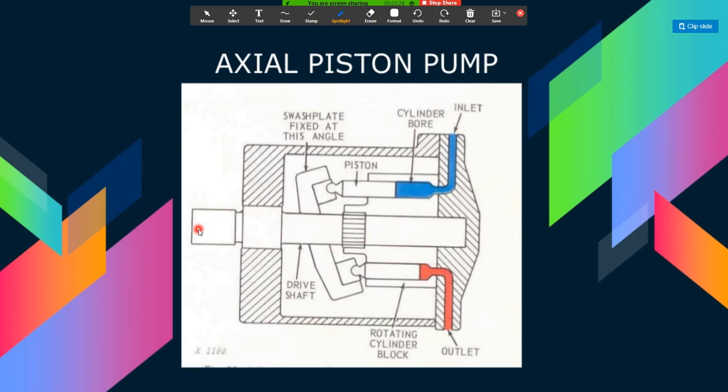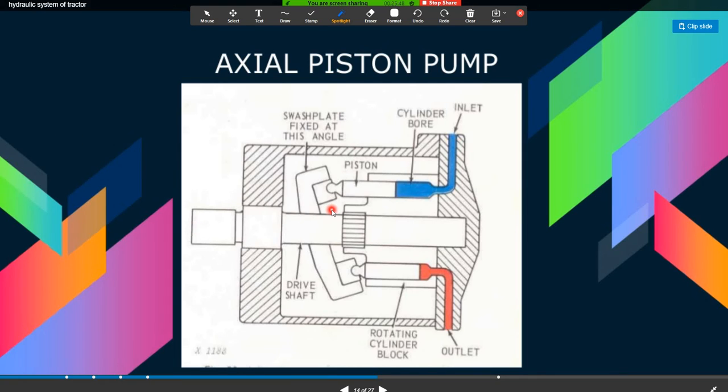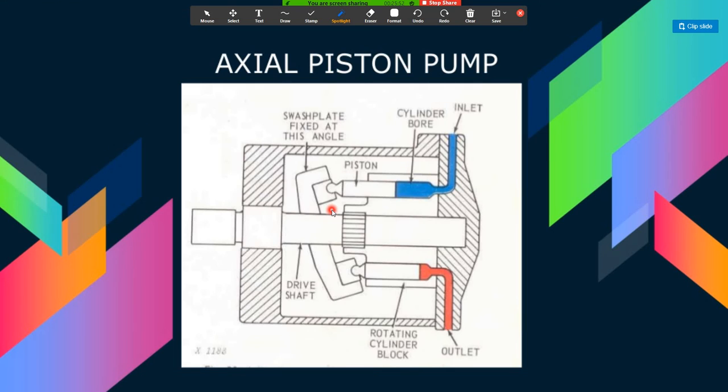The pump pistons, which are moved back and forth in their cylinders in the horizontal plane, are actuated by a plate offset at a fixed angle and possessing a cam action. This plate is known as the wobble plate or swash plate. A strong spring forces each piston against the wobble plate, thus providing the positive return at all times.